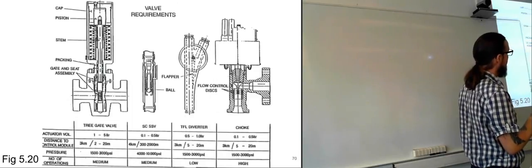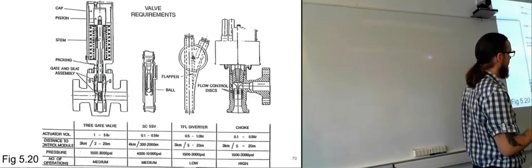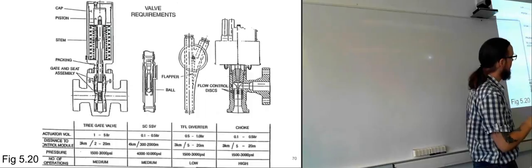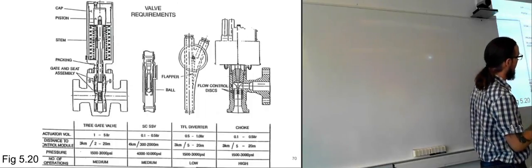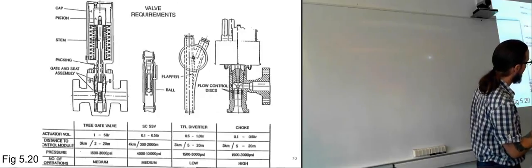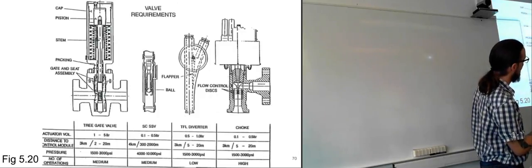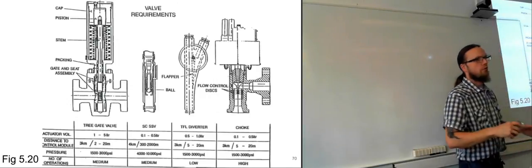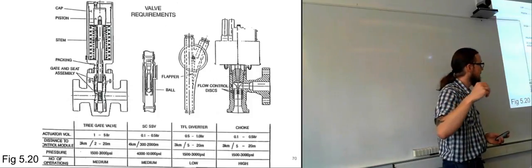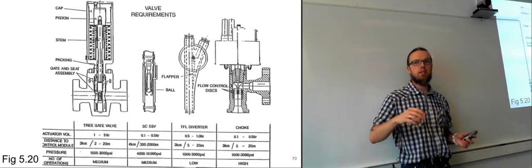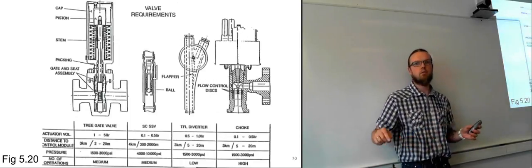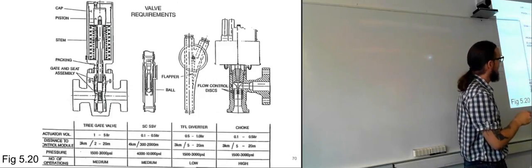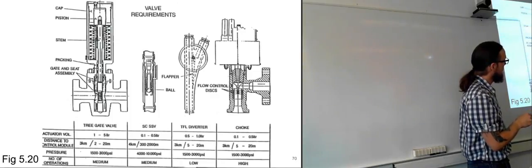So we also have the one we talked about a bit on Tuesday, the through flow line diverter, which comes right after the Christmas tree, basically, where the production flow is going through. I think the production flow is going through one of the lines here, and then if we are going to send down through flow line equipment and send it into the tree, it can't pass through the choke valve and everything, so it has to go through the loop and get up to the top of the tree and go through the valve on the top.